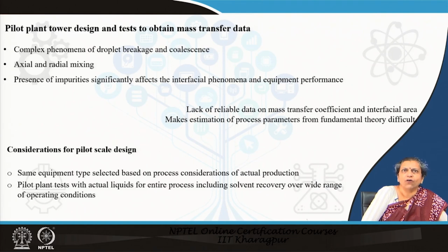Quite naturally, due to all these things, there is a lack of reliable data on both the mass transfer coefficient as well as the interfacial area. As a result, the estimation of process parameters from the fundamental theory, that is from the basic mass transfer equations which you have learnt in your mass transfer class, is extremely difficult. And so, in order to obtain data on the mass transfer coefficient as well as on the interfacial area, generally we perform tests in the pilot plant.